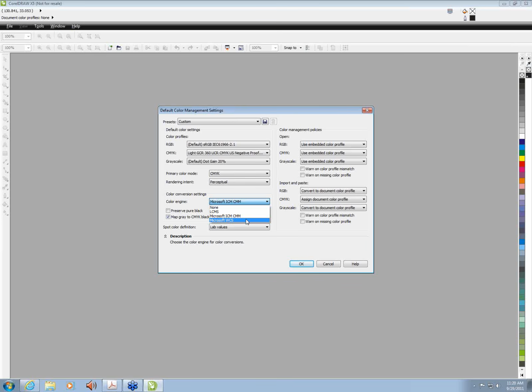But if you're really sensitive, CorelDRAW X5 does support the Adobe color management module. You can download it and install it. It is not ACE. ACE is what ships. You will have to go in and modify manually the black point compensation. The problem with ACE and the problem with Adobe CMM is that it uses black point compensation with the screen, and you can do nothing about it.